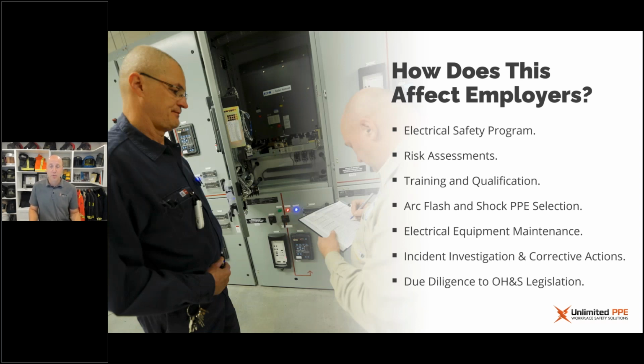How does this affect you as an employer? Of course, it has everything to do with your electrical safety program. That is by far the most important element that would be impacted with the publication of a new standard. How you go about your risk assessments, and by extension your program, would include the training and qualification requirements, and arc flash and shock PPE selection.